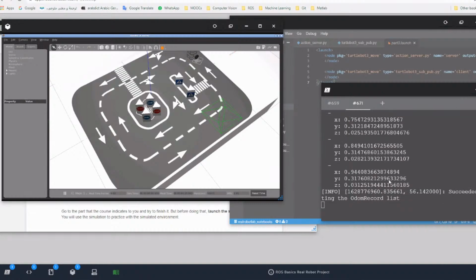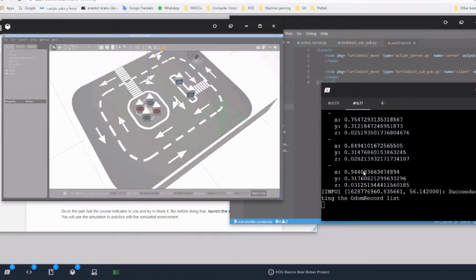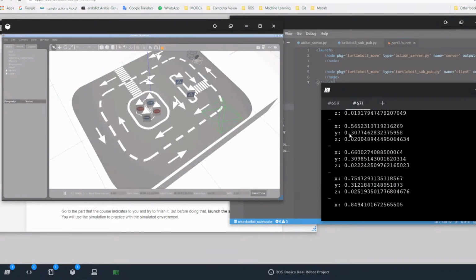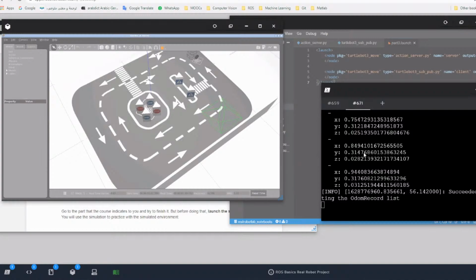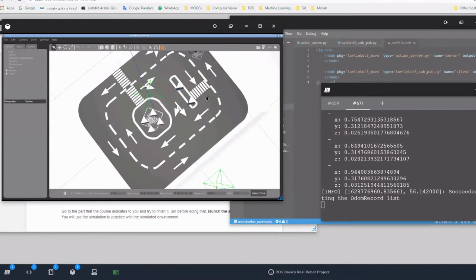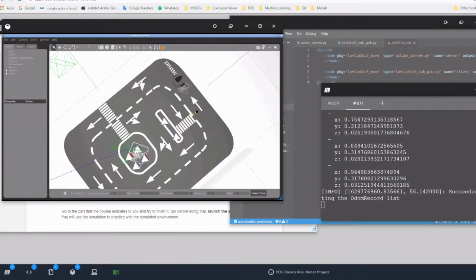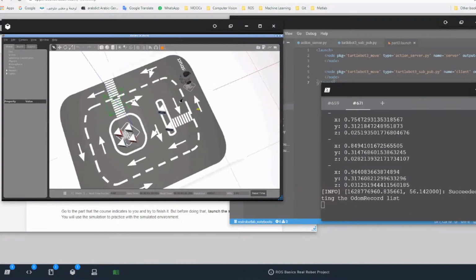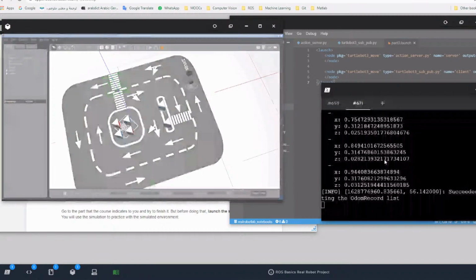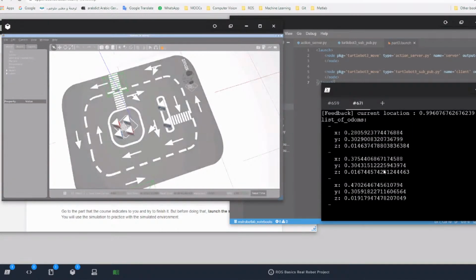And lastly, you're going to get the whole odometry message, one by one until it stops. Oh, and then you can see that if you're publishing at one every second, it looks like it's moving at 0.1 velocity. So you published at 0.1 for the cmd_vel, correct?